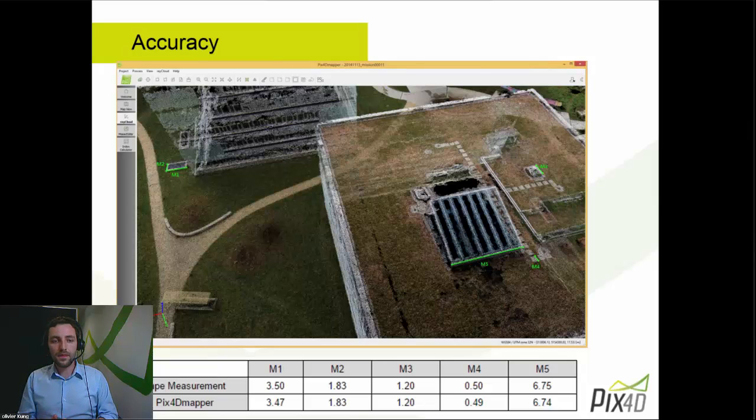So the conclusion is you can achieve centimeter grade accuracy with the Vision, and if you need global accuracy, you will need to use at least 3 ground control points. I recommend you watch the full webinar which is about ground control points, to get more information about that.